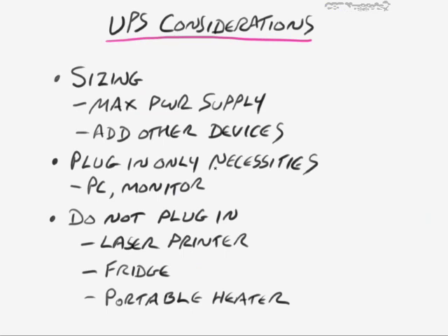No, what you want is something that's going to be able to properly cover your needs. So you need to size it in a similar way to what you do for selecting a power supply in the first place. Remember, you only want to use a maximum of about 60% of the available wattage of your power supply, and it's somewhat of a sliding figure. Depends on what your budget is and so forth. But you certainly do not want to get a UPS that is going to be rated at exactly the same as your power supply.